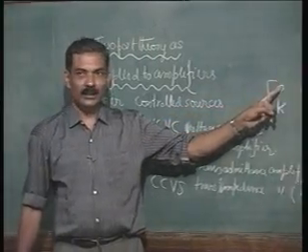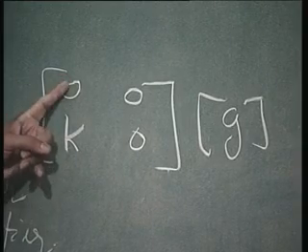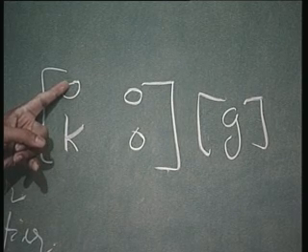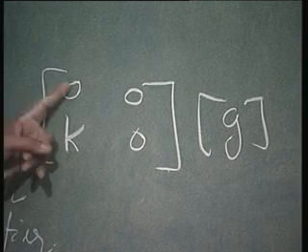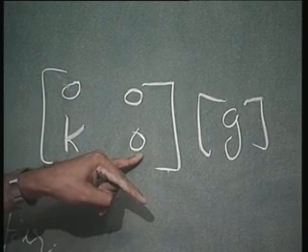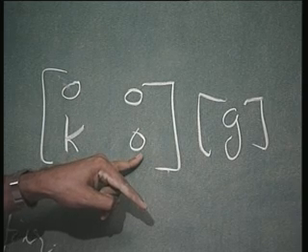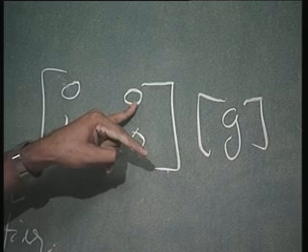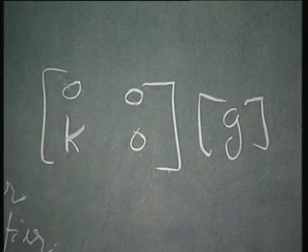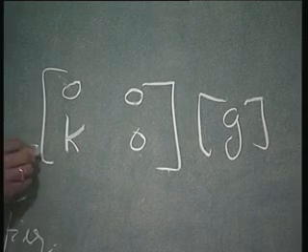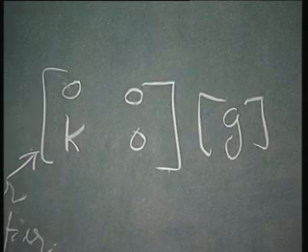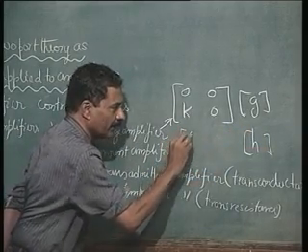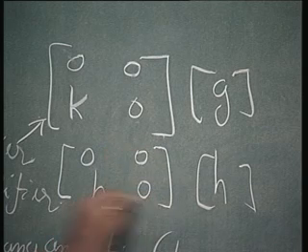If you see this here, this will define G I, which is going to 0. That means the impedance is infinity. This G is going towards 0, that is the output conductance. So it is a voltage source. It is unilateral, so no reverse transmission. So these things are going towards 0. Again, this is the representation. Therefore, for current amplifiers, the dual of this, the H parameter is the only parameter which is suitable for representation. No other parameter is suitable.